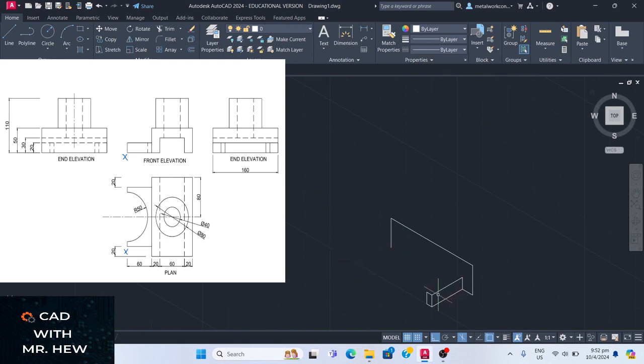All right. So we're gonna draw a line from here to get the semicircle from here. Going up there, this measurement will be 100 millimeters. Enter. Right? Then at the 100 millimeters, it would go down 20 millimeters. Good. They would go across 10 millimeters. Enter. Then it would go up 20 millimeters. Enter. Then it would come back 10 millimeters this way.